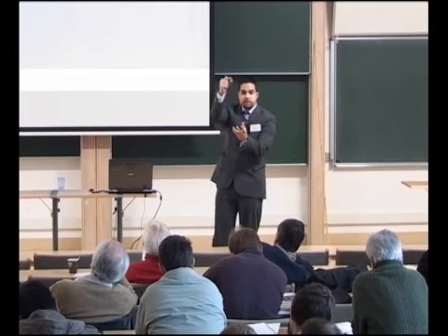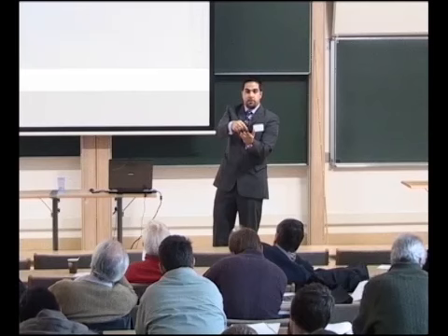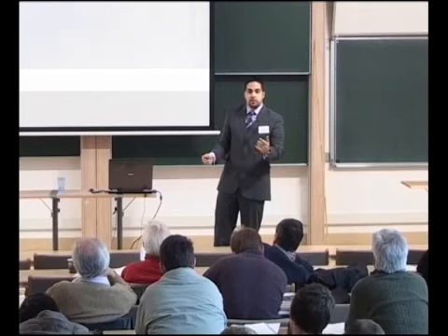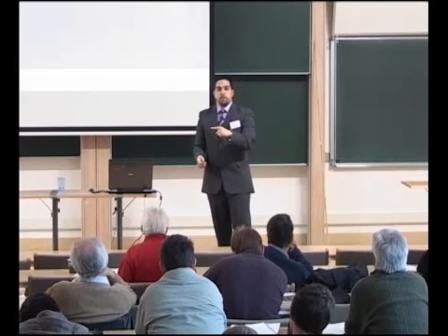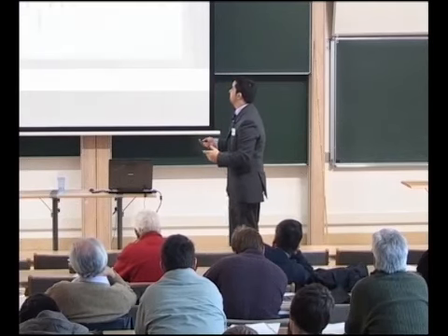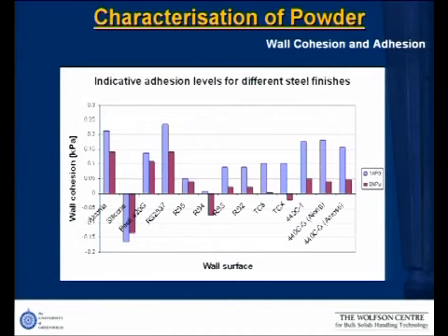friction between the material and the wall of the dosator, or the cohesion properties of the material, the dose is just going to slip down, it's not even lifted, and you get an empty dosator. So to know how the powder behaves with the material of the dosator is very important.